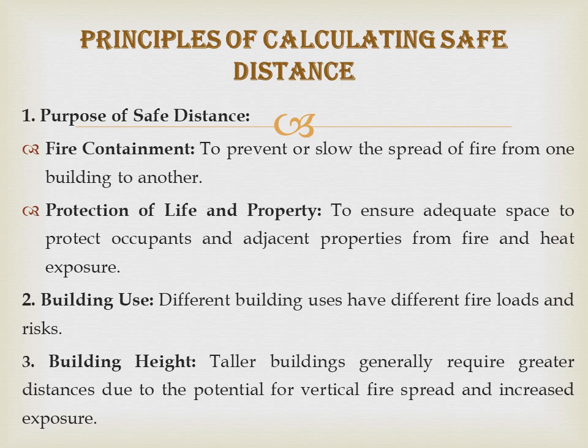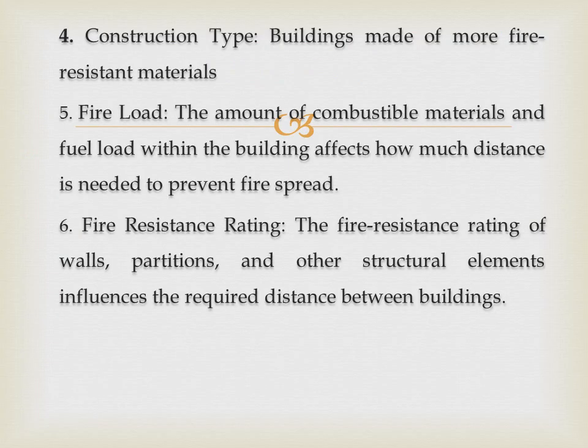Building use. Different building uses have different fire loads and risks. Building heights. Taller buildings generally require greater distances due to the potential for vertical fire spread and increased exposure. Construction type. Buildings made of more fire resistant materials.